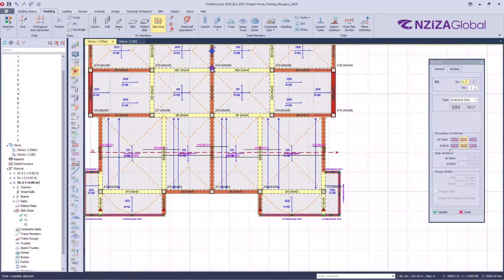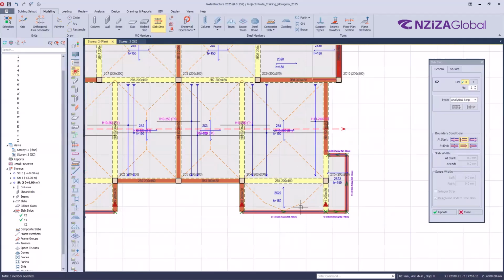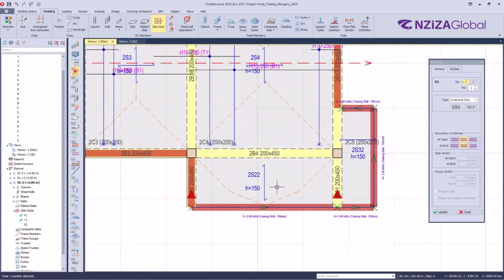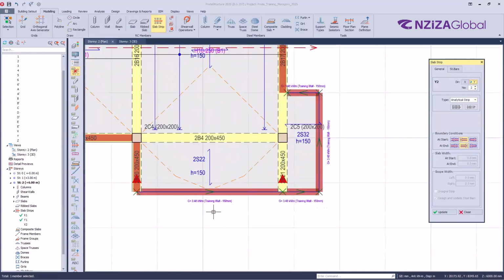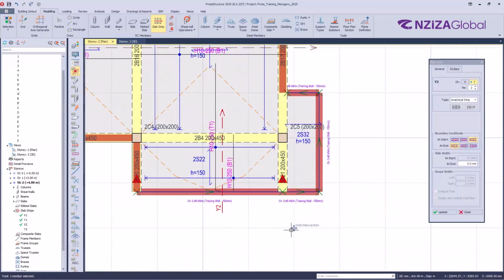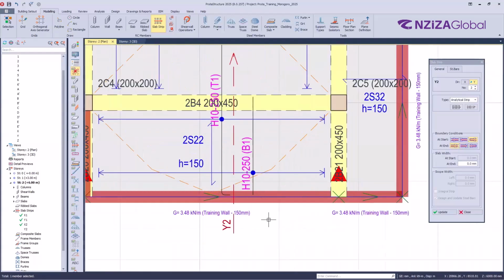Are you able to understand these boundary conditions? Because they are very crucial. So let's suppose I want to design this cantilever here. Okay? This cantilever here. It is in Y direction, right? Then the condition here will be cantilever. Good. And I will end the strip here. The condition will be continuous. Great. Then I can draw like this. And the reinforcement will be placed.